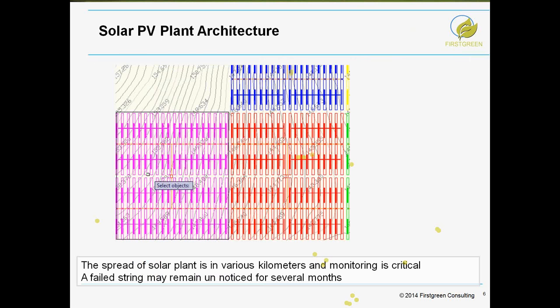So you can have a particular solar PV plant structure in various fashions. Suppose the plant is of larger size. For example, this is a snapshot of some 30 megawatt plant, and what we are finding is these blocks, which are representing something like 1.6 megawatt each block, and this design had string inverters, so you are not finding an inverter in between.